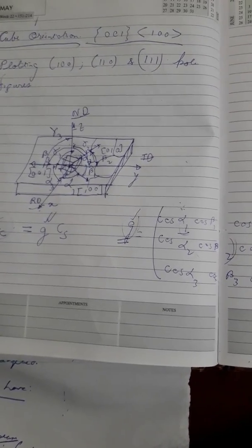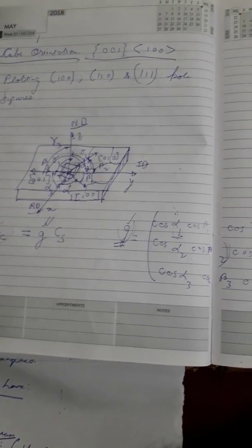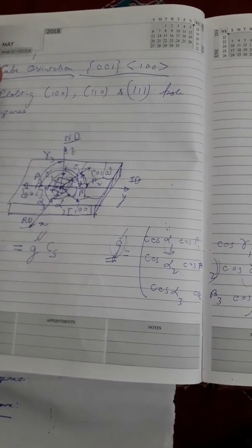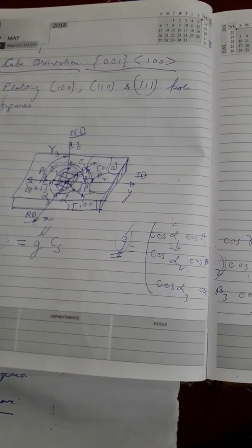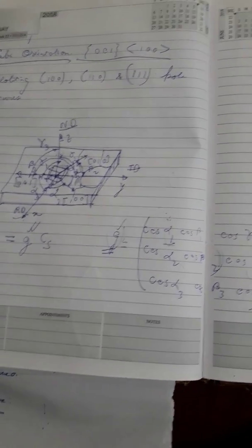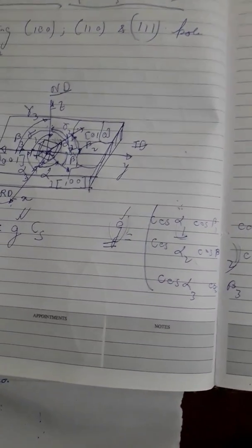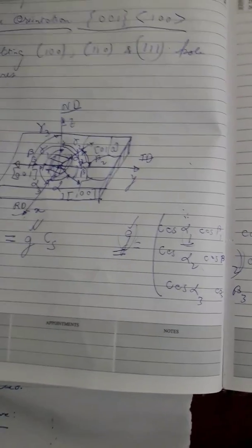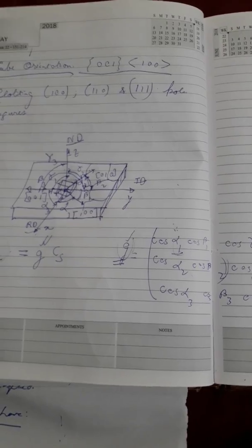When we talk of texture, we generally talk of representing texture by 4 methods. The first is the determination of the orientation using the G concept. This G is basically nothing but the orientation or rotation matrix. Secondly, we talk of the angle axis representation, thirdly the Rodrigues vector to represent orientation, and fourthly and lastly the Euler angles.